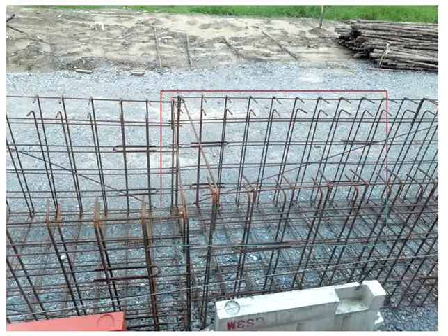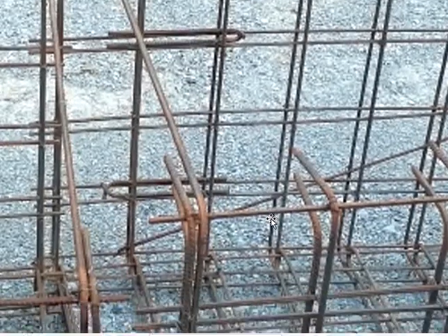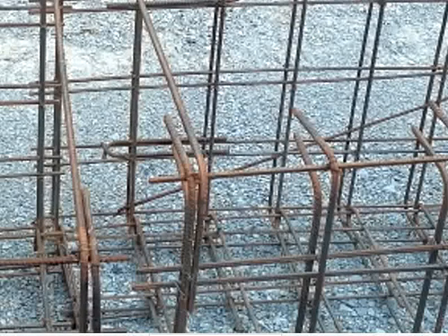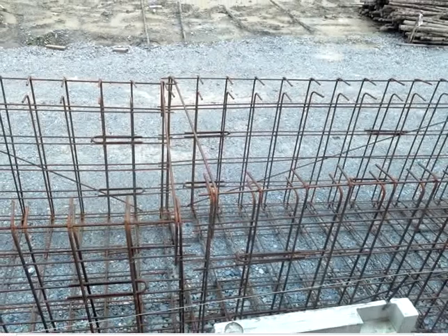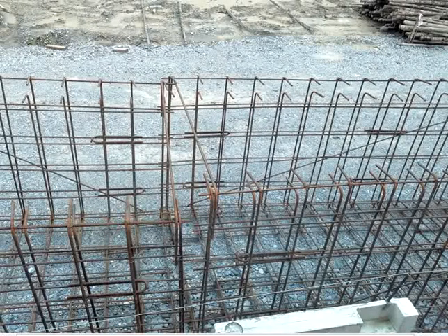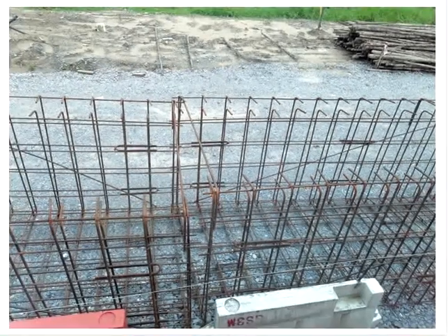This is an example of the reinforcement bar for concrete drain. If you look closely at the reinforcement bar, they are all high yield steel strength. You can see the ribs on the surface. And then there will be double layer of reinforcement. By looking at the size of the reinforcement, taking this as an example, this will be the Y10 rebars, and this is most likely Y12 rebars, which can be quite heavily reinforced. For a typical drain of this size, this amount of reinforcement bars are provided.